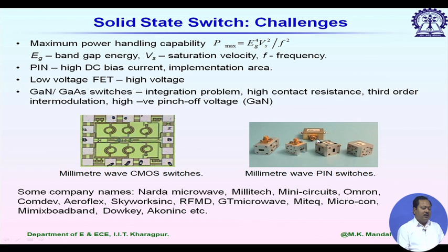Right hand side pictures show several PIN diodes with their packages. So, they are based on rectangular waveguide technology. Inside the rectangular waveguide, the PIN diode is housed. You can see for a given component, this small aperture shows the input line, we have the output line on the other side, and the SMA connectors are actually used for the biasing or the control signal.